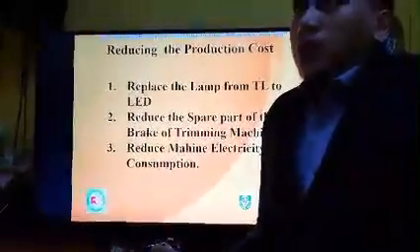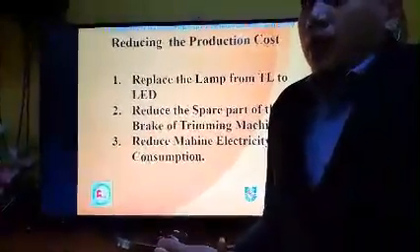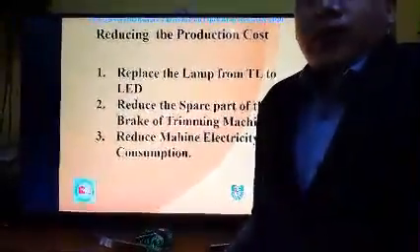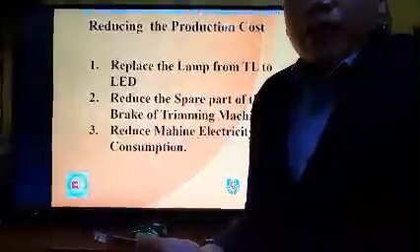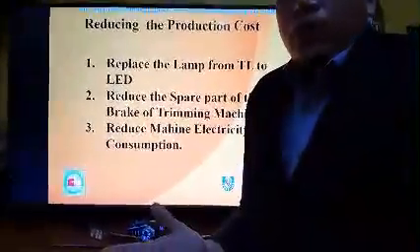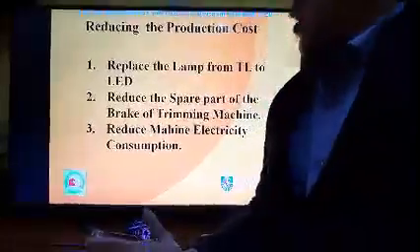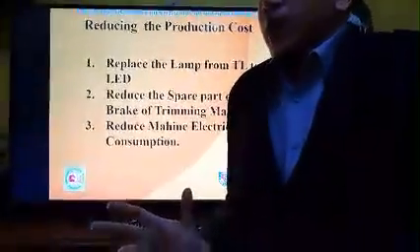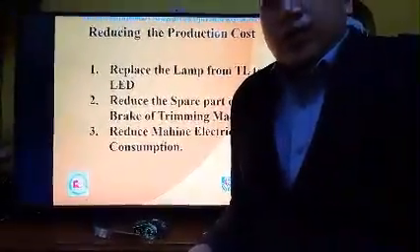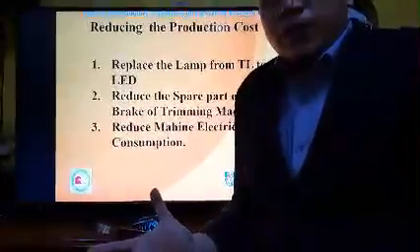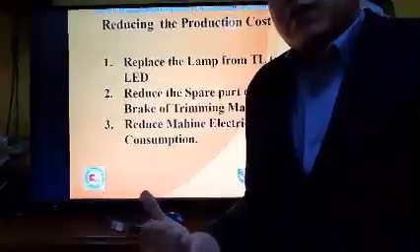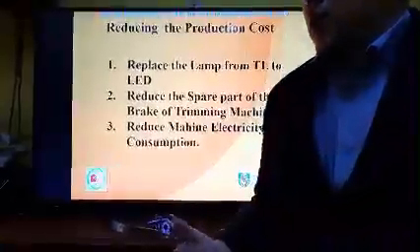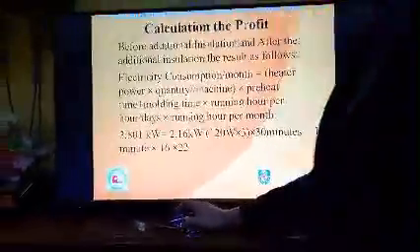If we use 3 heaters of around 200 watts each, there will be high power consumption per day. So we can modify and reduce the preheat time by giving the machine the best insulation, so a faster preheating process can be achieved. Okay, now we go to the calculation.